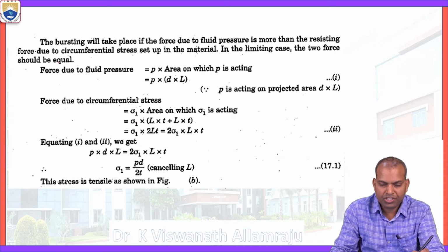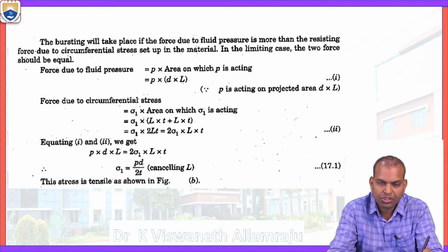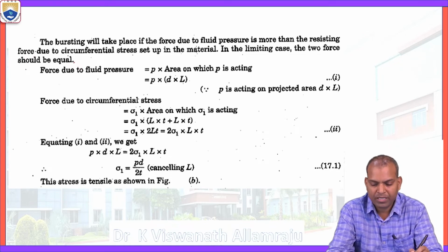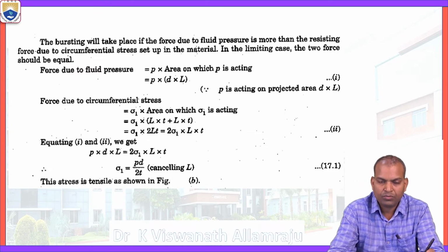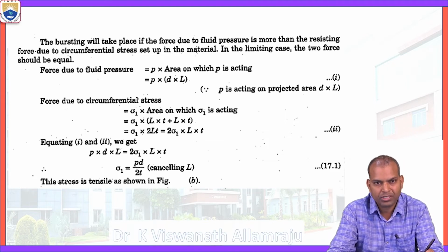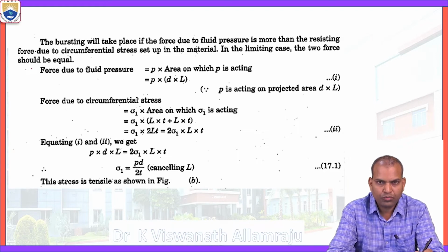Bursting takes place when the force due to fluid pressure is more than the resisting force due to circumferential stress. So the two forces should be equal; that is the limiting condition.